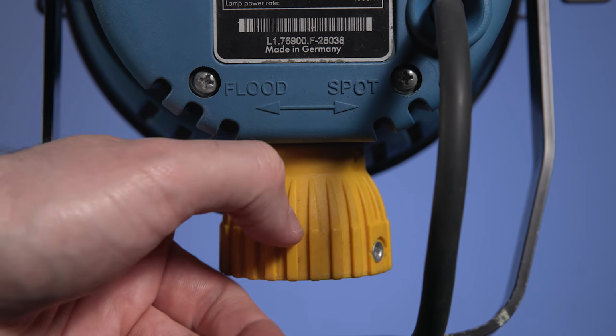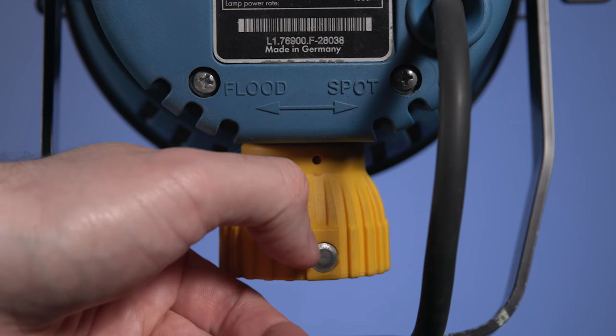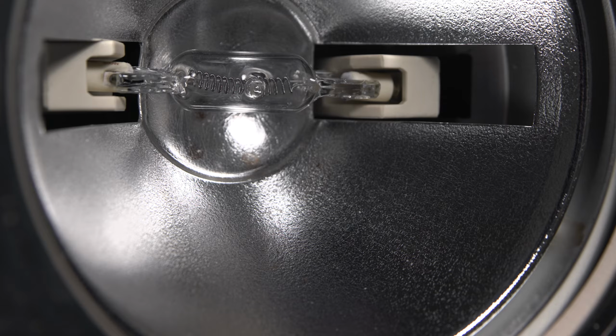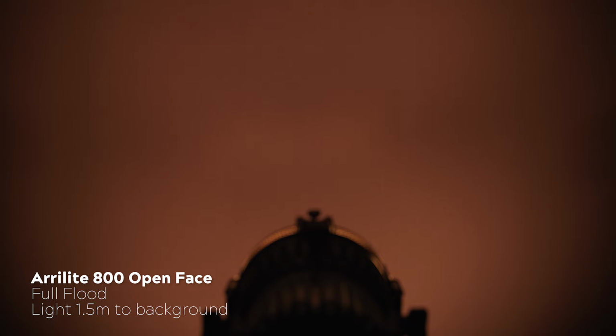You can control the spread of light somewhat using the flood and spot function, which will move the reflector dish closer or further away from the bulb, narrowing or widening the beam angle. The reflectors will often have a textured quality to them and are generally spherical in shape rather than parabolic, so the beam won't be particularly even. This will usually result in a fall off in intensity towards the edges of the beam.